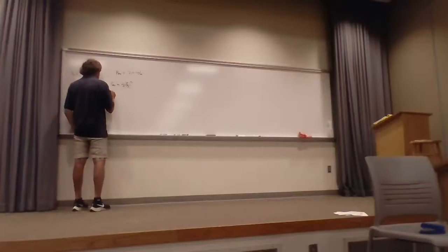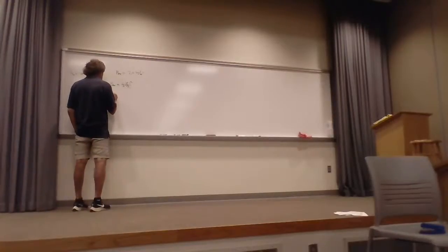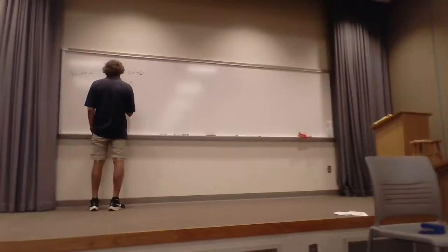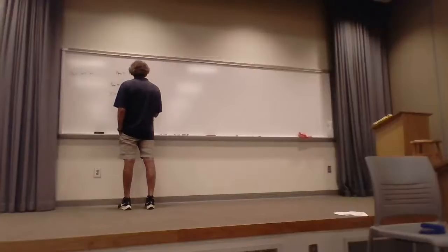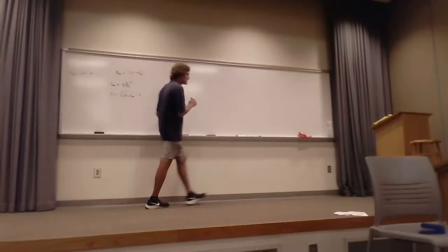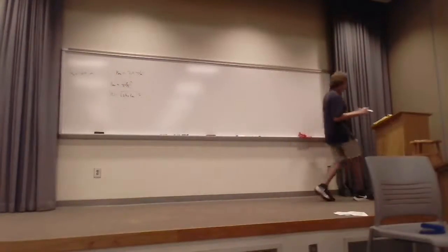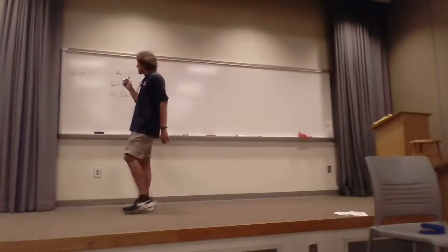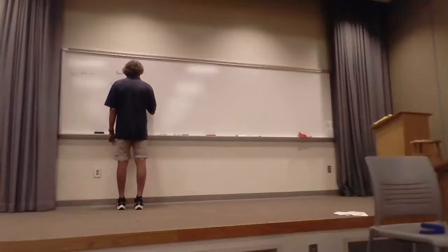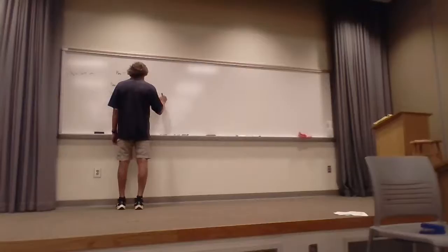So to get the E field, it's going to be the magnitude of the E field, the square root of 2 eta naught times P average. And you can do this, just put in 125 times 20 times 2. I want to say it's 133, but I don't remember exactly. Can you tell me what it was? 122.8, and that's volts per meter.